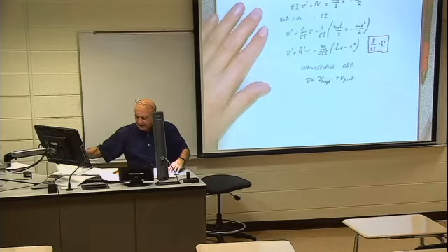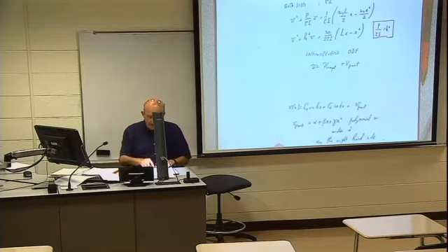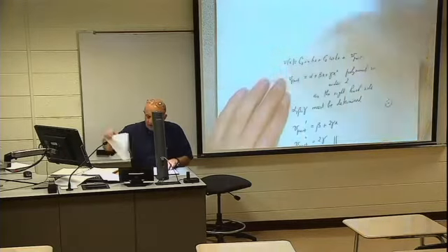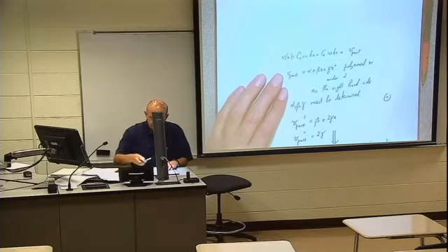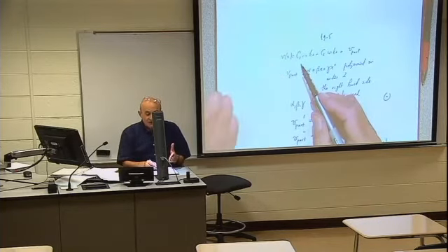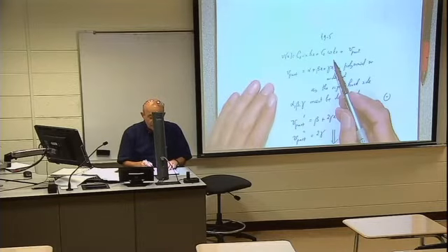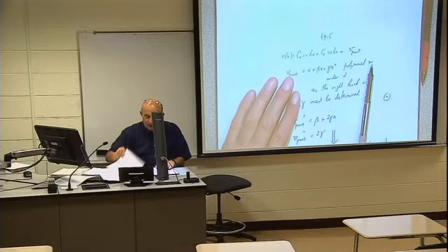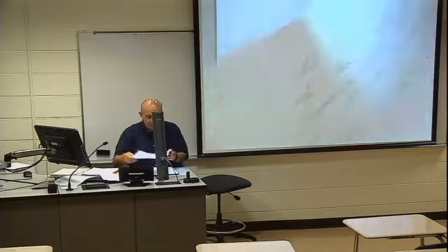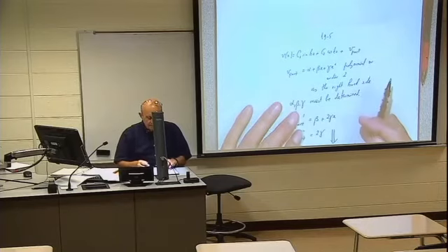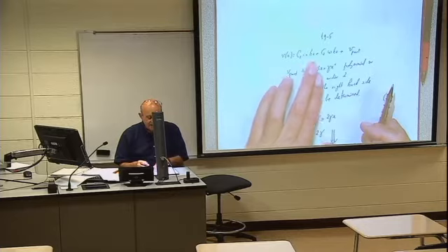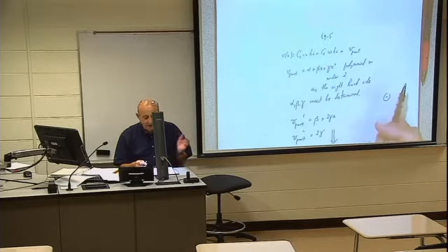Okay, now we are talking about the homogeneous problem. The homogeneous solution we already know. That is in lecture 13, when we dealt with just buckling. V of x equals C1 sine kx plus C2 cosine kx, plus V particular.